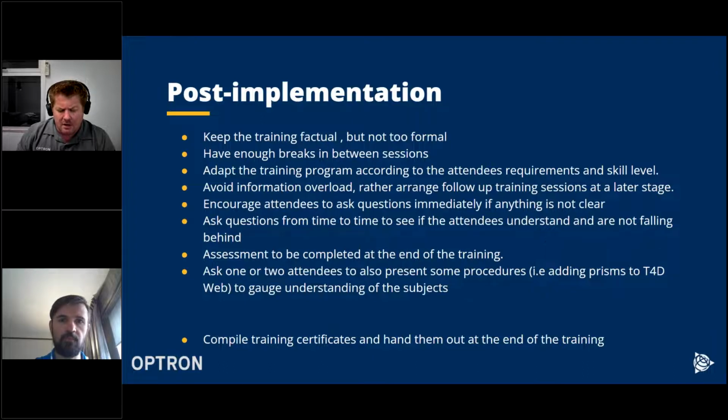But if there's none, we try to install solar as a last resort. So we first try to push for a permanent electricity supply, and then if the customer says it's really not available, then we'll go for solar. And we normally install 200 amp hour batteries in that cabin. So if you only have a total station, without sun it will probably run for at least 2 or 3 days. So you have that kind of backup just in case the solar can't give you full 24/7. That's correct, yes.